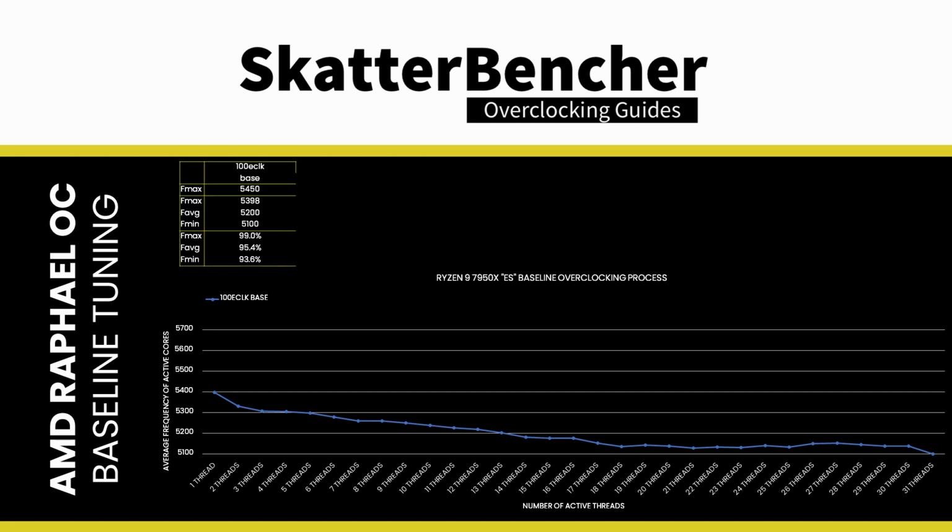Our baseline configuration is with Precision Boost Overdrive enabled, which unleashes PPT, EDC, and TDC, and a 100 MHz external reference clock. Please note that I'm using an engineering sample CPU, so the boost frequencies don't match the retail CPUs. That said, the general tuning process still applies to retail CPUs.